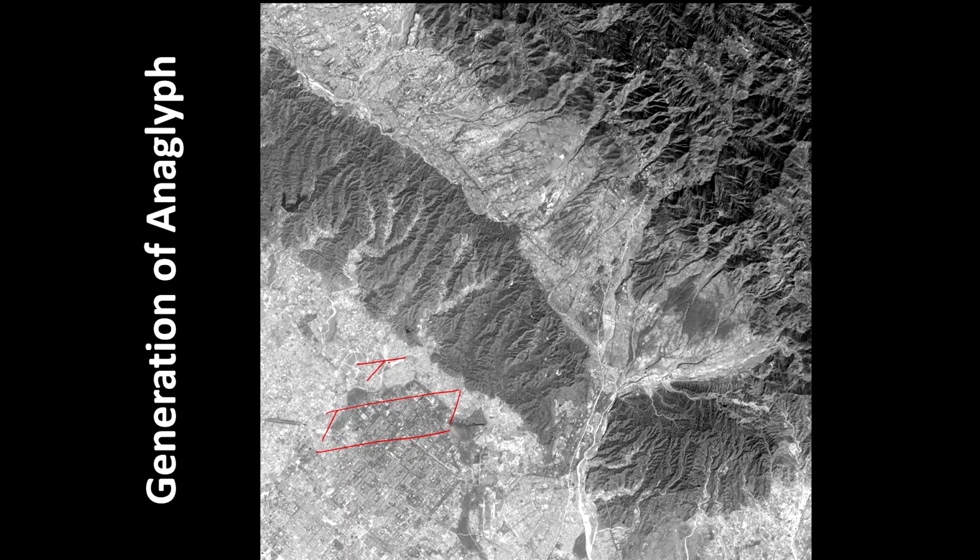You can take photographs of the same area with 2 different cameras, and they can be overlapped. The overlap should be around 40 to 50 percent. Even if you fly like this and come back, there has to be an overlap sideways also. This overlap will help you in viewing the terrain in 3 dimensions.